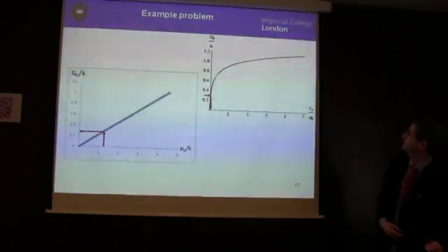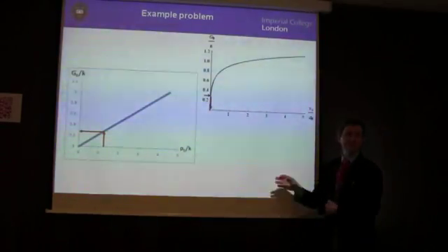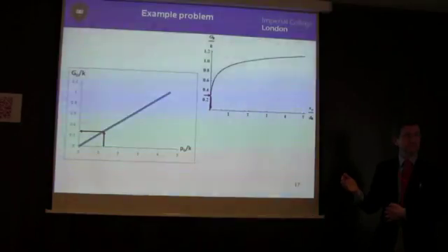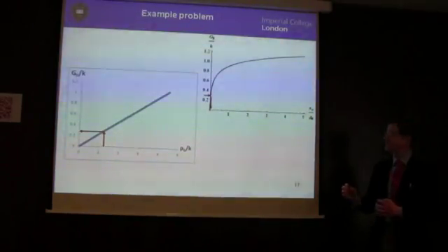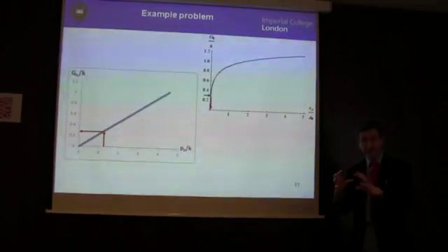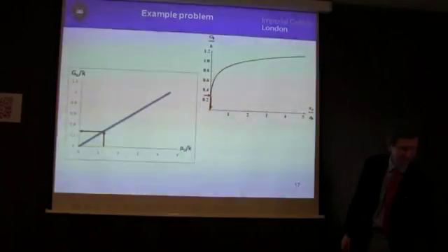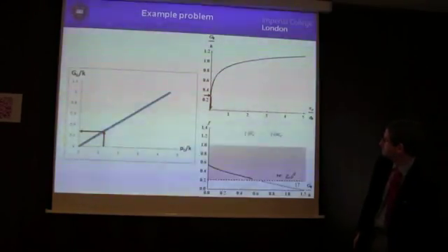And if you put that value of G0 on this scale, you can calculate the size of the plastic zone. Okay? So you're now using the calibrations that I've already found within Williams' solution, and you can say explicitly how big the plastic zone is going to be.